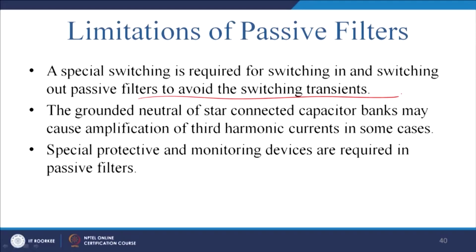And also you generally take it out, but there is a problem, because the capacitor current and voltage are 90° phase shifted. So, it is not advisable to take it out at the zero crossing or at a peak. If you say I will take it out at the zero crossing of the voltage, fine, but the current is at peak, so the inductor will create a problem. For this reason, what we generally do is take out or insert these filters when voltage levels are the same, then we insert with the nominal value of the current, not at the peak value of the current.